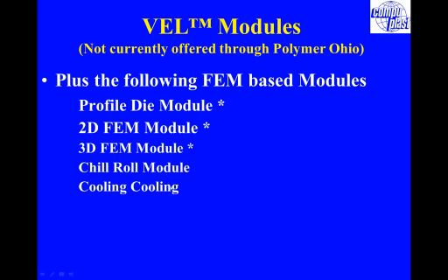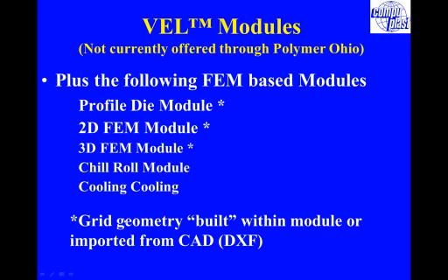The cooling module is still also based on finite element analysis, and this means that we can build the geometry within the module, but that's rather inefficient. Rather, what you do is you import a CAD file, or start with a CAD file, create a mesh, and then import the mesh to perform the calculation.